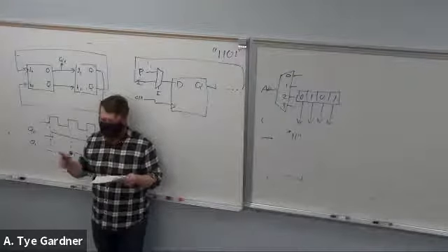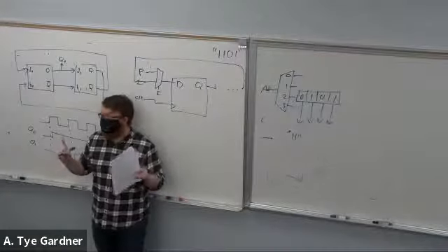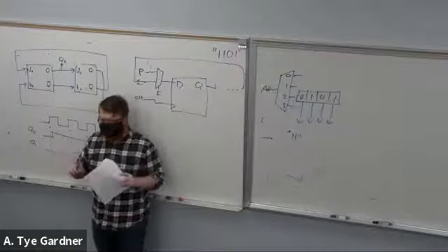So I would have asked you to declare sum. And then line 35 just says end, it should say end behavioral, right? Line number 29 is not a syntax error. It will give you a warning, it will not give you an error, right? So that was kind of the one difficulty in this whole thing. The biggest issue I think people have is falling for that, and not correcting it, right?